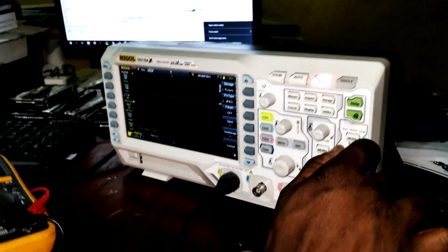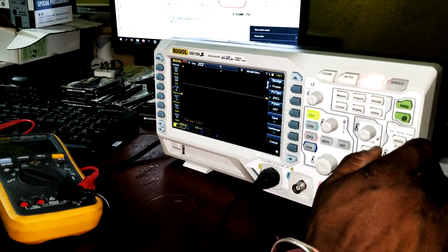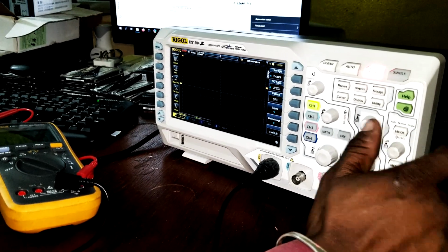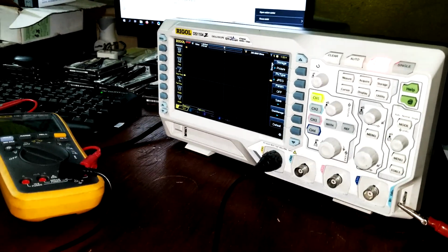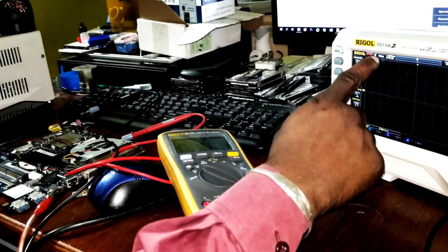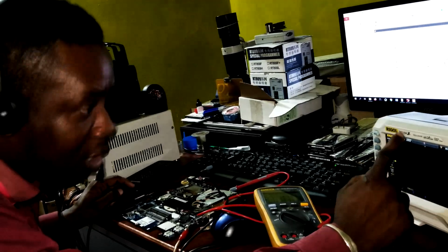We're going to check the RAM SMBUS, the SMB clock and data signals, which are an I2C bus. Any SMBUS is I2C bus compliant, right? So let's check. I have already set up my oscilloscope at 1 volt per division, right? My time base is set to 100 microseconds. It can go between 100 and 250 microseconds. So we're going to check, right?